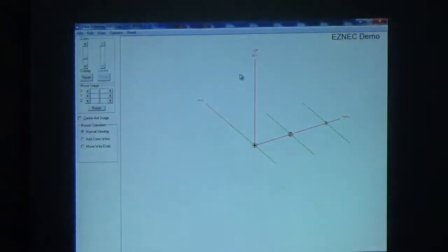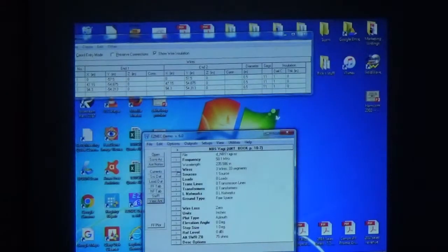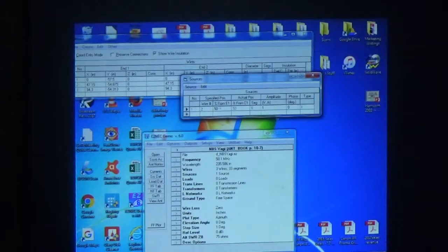So, there you go. That's on the ground. So he's got, and 1, that's not a source, but that's 1, 2, 3 source. So anything you can pretty much visualize, you can model. And that's a Yagi, why does it have multiple sources? Because they're going to be parasitic? It doesn't. Before I say it doesn't have multiple sources, I'm gonna come here and see, it only has one source. And that's on wire 2. So that's the driven element, with the reflector and director.